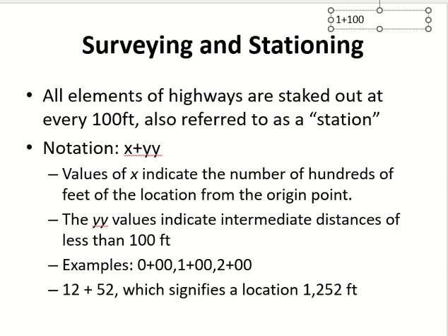Here they call it, the Ministry of Works, or in Bahrain the term is chainage. So this means 1 kilometer plus 100 meters. This means 1 kilometer plus 110 meters, and this means how many? 110 meters. So the number after the plus sign is meters, the number before the plus sign is kilometers.